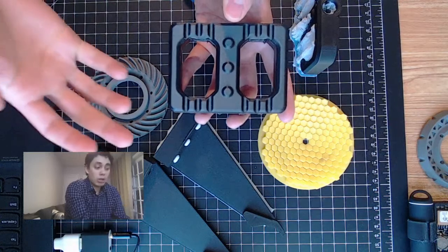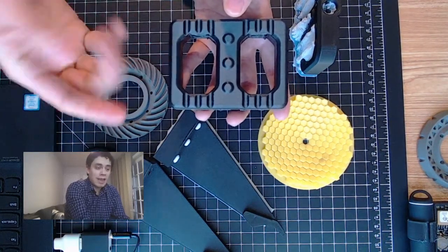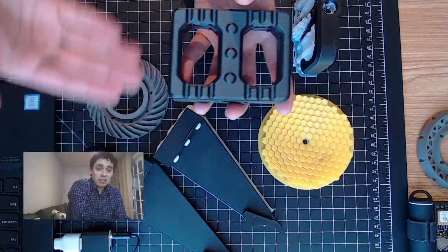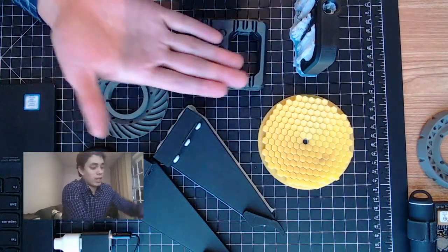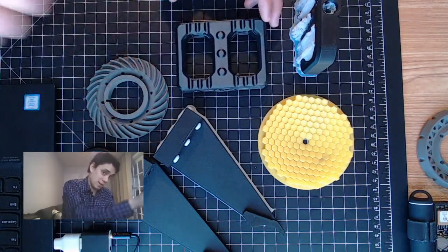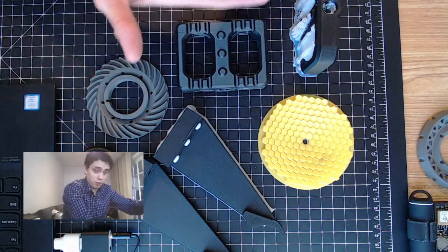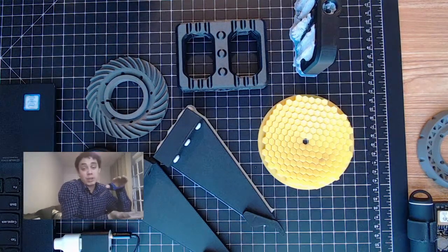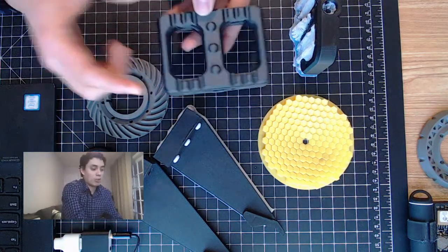So all in all, for this particular use case, a flat alignment would be better, just because then the layers are stacking up against each other. If you imagine the layers being sandwiched against the perpendicular force, as I'm applying the force, it's compressing those layers as opposed to shearing them, as would happen here.